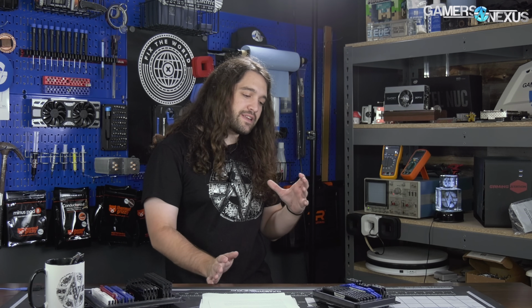And that's because it's sitting there retrying different timings over and over until it finds one that is stable for the motherboard. And what's actually happening is the IMC will try a variety of different settings in an attempt to stabilize the system. Not all of them are timings, and that's at each boot of the system. It's an important point for even non-overclockers because, again, if the memory seems unstable, just cycle it a few times and see what happens. Maybe it'll work and you'll get lucky. Retry buttons are an excellent tool for making this work.